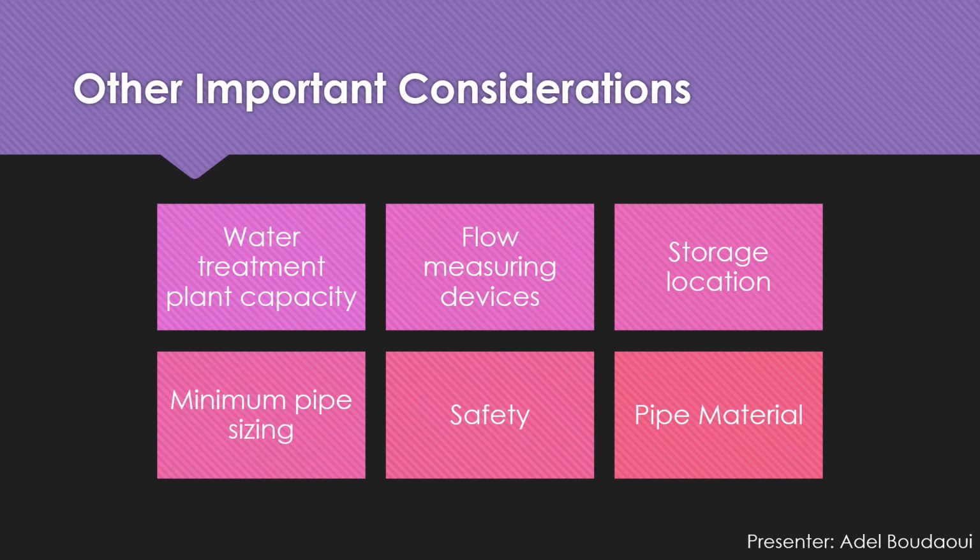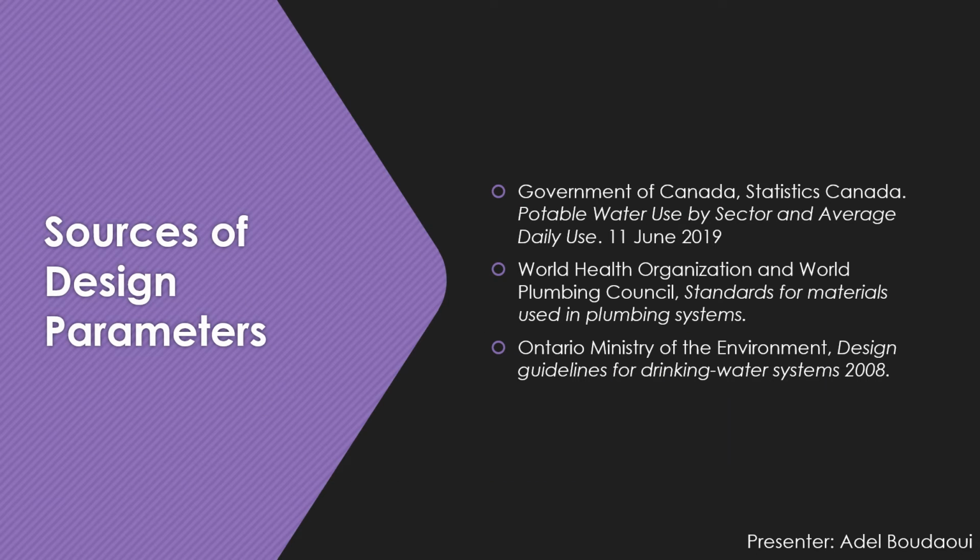Per the Ontario Building Code and Ministry Design Guide, a minimum pipe size for the main branch distribution of water is 6 inches in diameter. The distribution system, regardless of design, must be safe. Redundant pumps, pressure relief valves, and design for isolation and serviceability are incorporated into the building. Galvanized steel is the selected material for the bore well and water distribution system since it is readily available in standard sizes and corrosion resistant. Rate calculations. Statistics Canada data for the year of 2019 were used as no in situ study was possible.